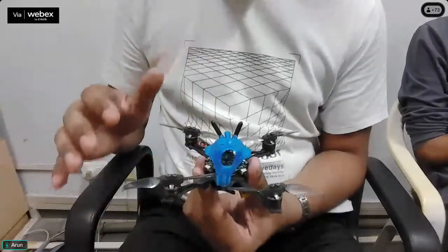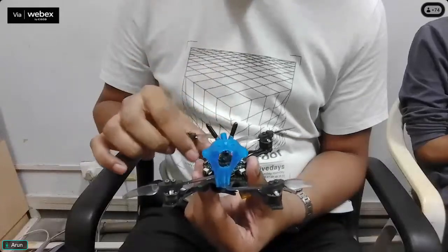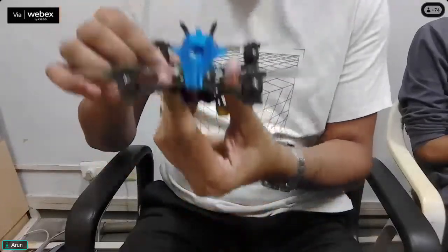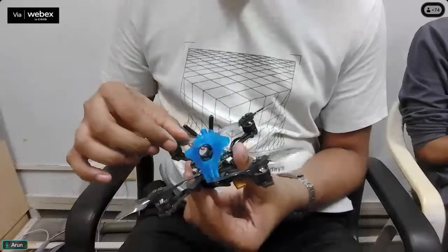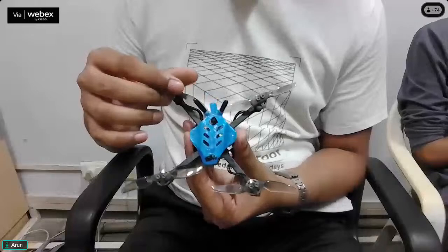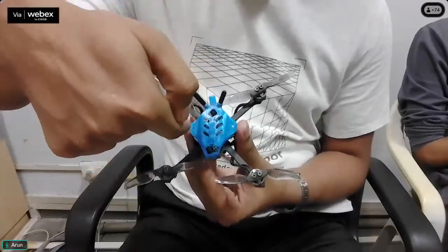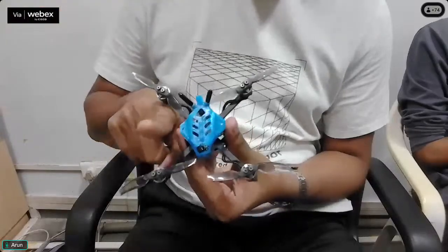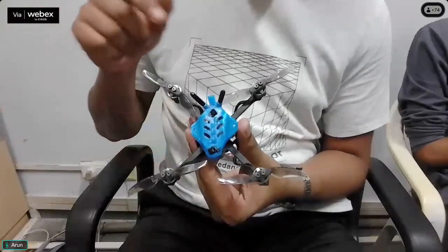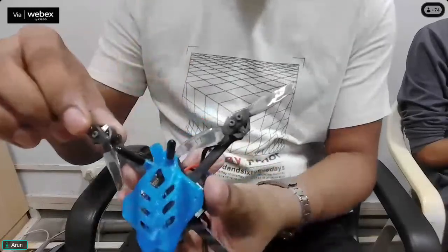When you are not doing any roll, pitch or yaw, the force is pointing upward and your motion will be in the z-axis. But when you roll or pitch forward, the direction of the force will be tilted, and this will allow the drone to move in this direction.